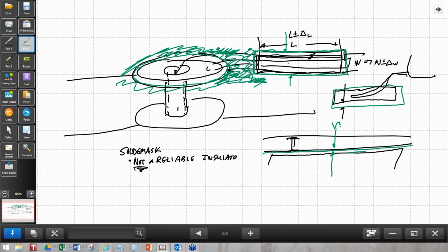First, when you put it down, it's so thin that it can be mechanically damaged and actually short out. Second, it can have pits and voids in it, so that if there was, say, a little bump or a little something, it's actually air, it's not the material. Third, if you're using a liquid photoimageable type solder mask, then it may actually pop in the middle of a hole.